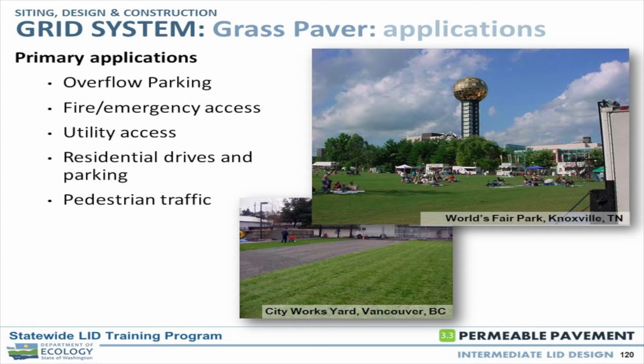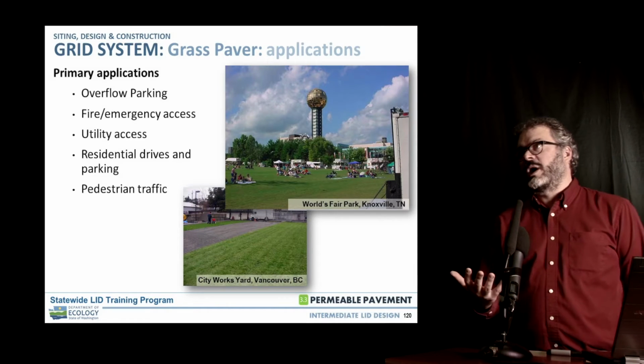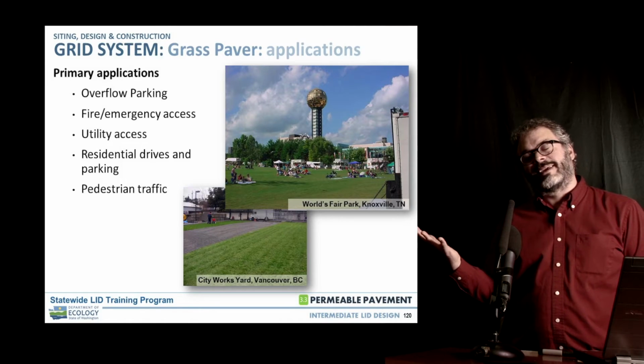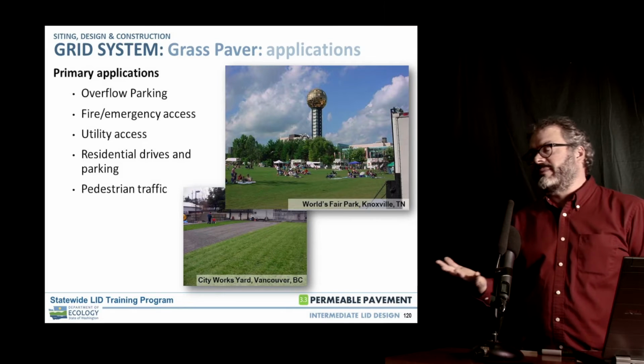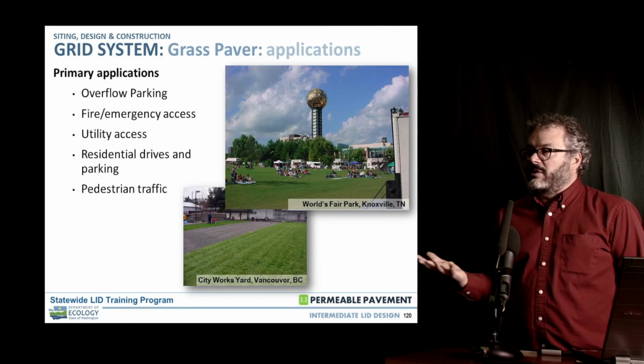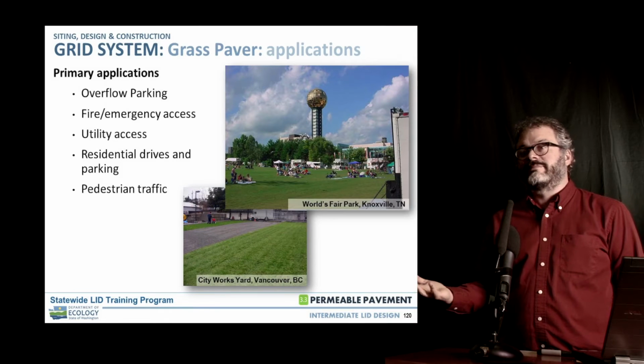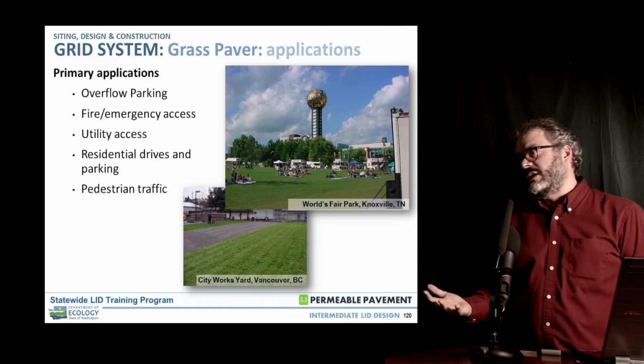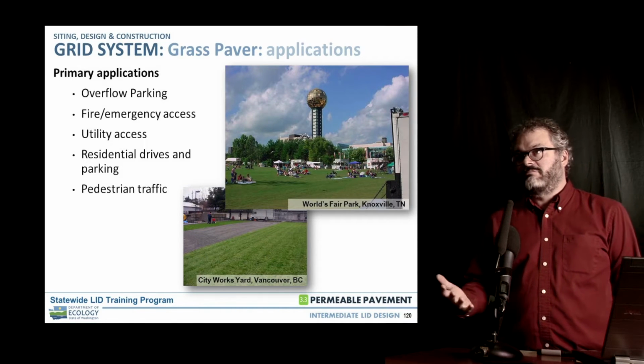And its application, unlike the gravel, which can of course be used without hesitation and without any real impact, more or less, to the system, grass not so much. If we want the grass to maintain a uniform green carpet, we cannot drive on it every day. It's not that the system stops working hydraulically. It really continues to maintain its stormwater function, and it probably continues to maintain its firmness as a firm surface. It's just that the grass dies and wears out. And so if you're willing to tolerate that, what is essentially mostly an aesthetic issue, then that's okay.